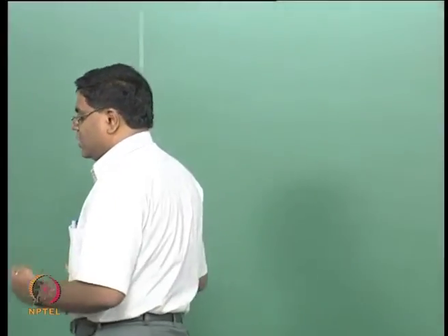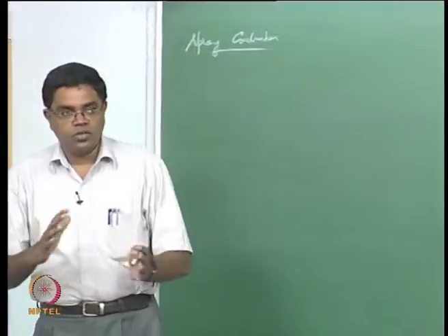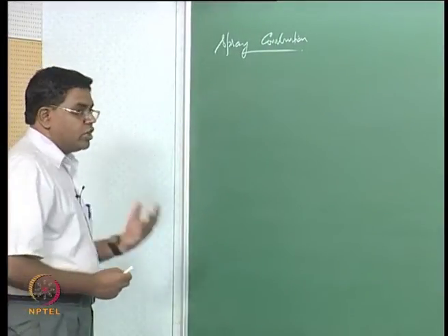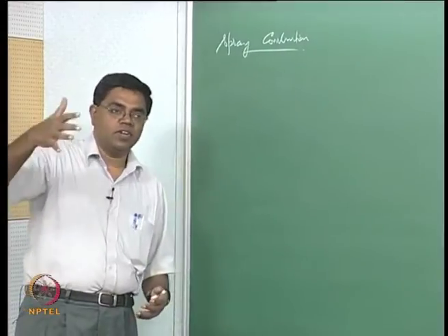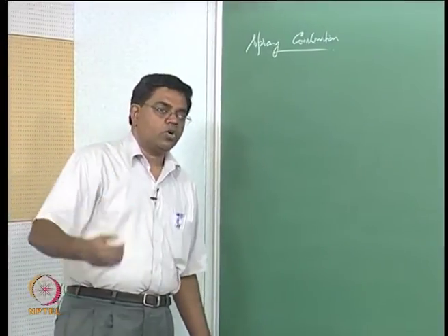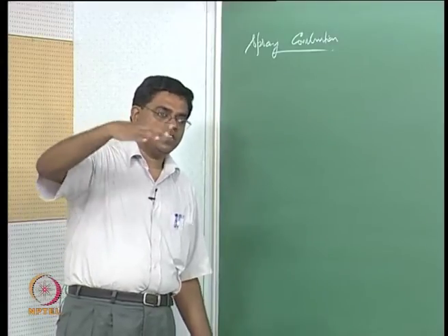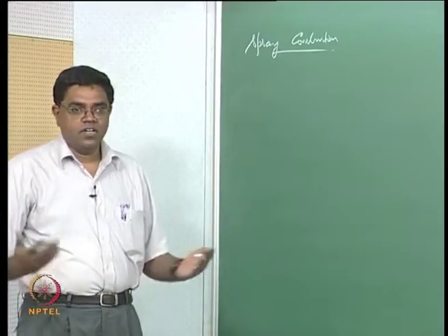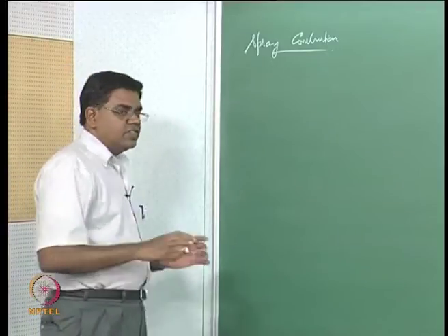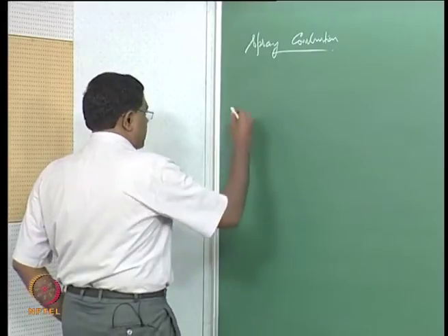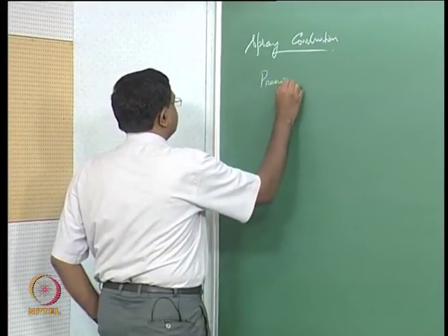In reality, as I said, you would have a combination of these two things. It's neither this nor that, and of course you can think about a partially premixed flame that is established in what could be nominally a non-premixed injection of liquid fuel, but since you have a standoff distance, it allows for some mixing. So many such possibilities exist in reality. So what we will first consider is a premixed mixture, for the sake of simplicity.